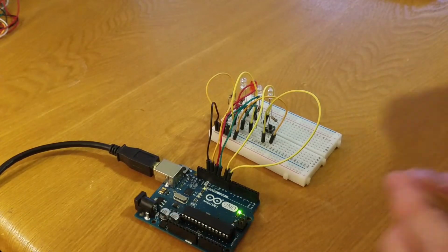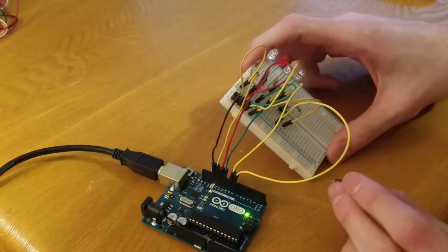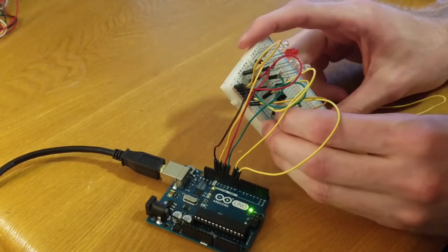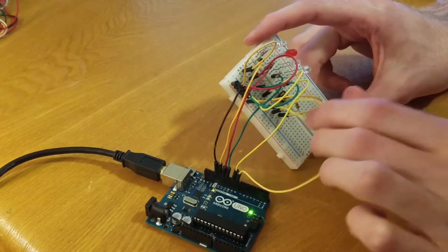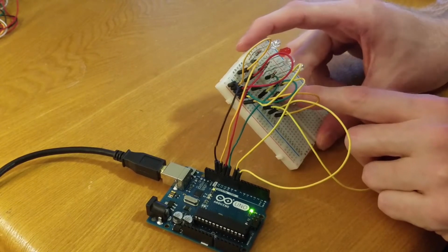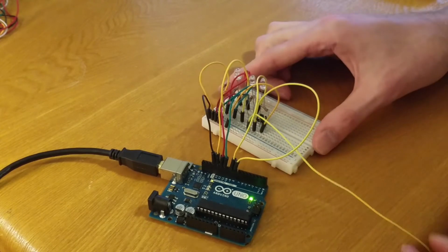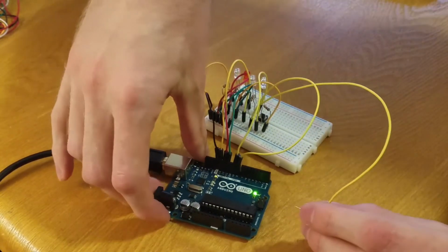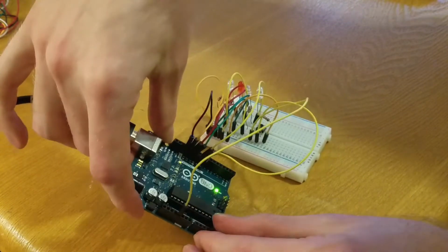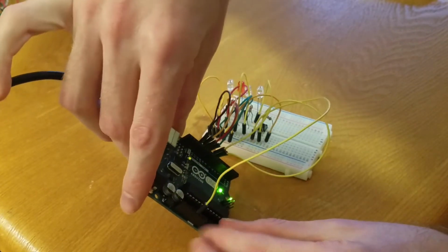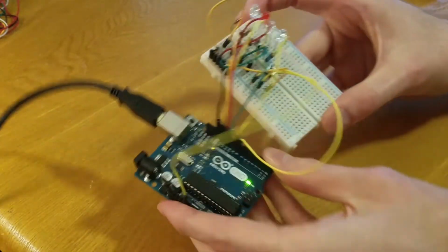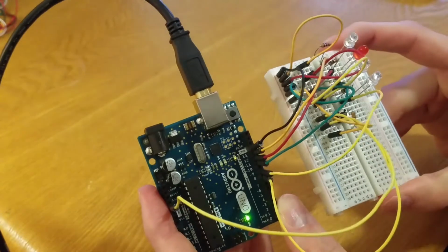The last one is we have to use our 5 volt over here. So for the 5 volt line, we're going to use a longer yellow one. We're going to go to line 13. So that's this one right there, line 13. That's the same line as the top of the button. And then that's going to go all the way over here to where it says 5 volt. Yep, there we go. All right, so move it closer so maybe you can see that. I'll try to hold it still.